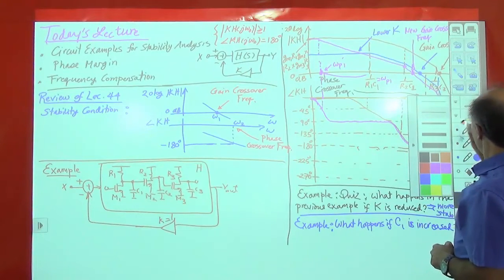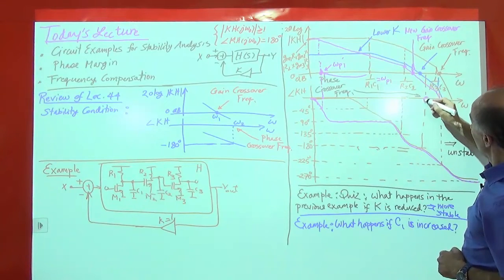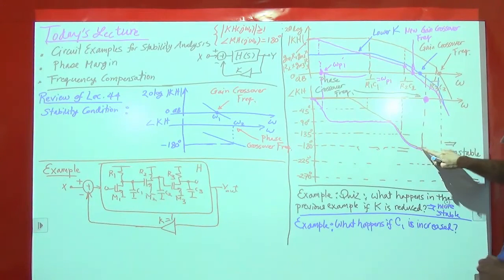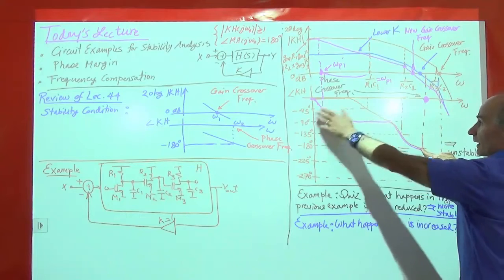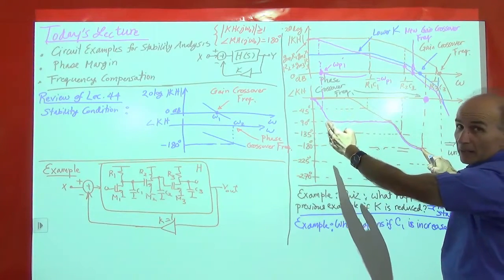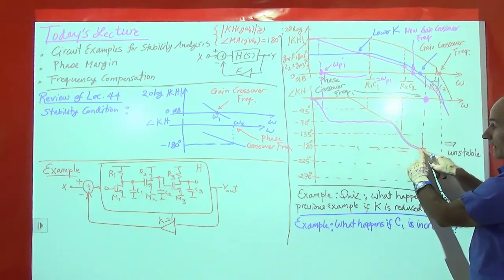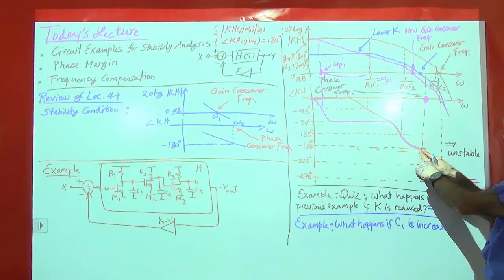And then we go back to this plot here. So it is this point. This point hasn't changed, right? Because we changed this part of the profile. But at this point, we are so far from this pole that it doesn't matter whether the pole is here or here. The total phase shift at this frequency is still minus 180 degrees.